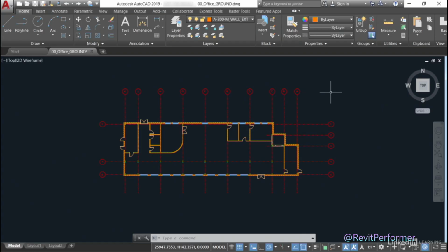So when you're working in your AutoCAD drawings to a known standard, in our case BS1192, make sure that you only give the information you need, but more importantly, you retain the information you need to still work on the DWG file. And that's really important if you're linking the CAD file, because the CAD file will still be worked on, and the next time you open up your Revit project, you'll see the changes to the CAD file if it's linked into your Revit project.